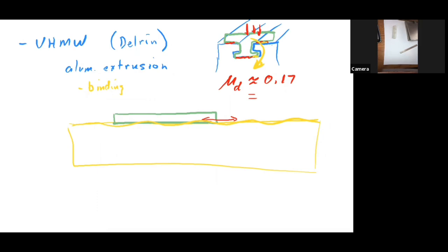So this large surface area ended up being somewhat of an averaging effect. It ran across the high bumps, so to speak. And the longer you made this part, the longer distance, the more it averaged out the bumps and the more accurate its motion became as you went back and forth.